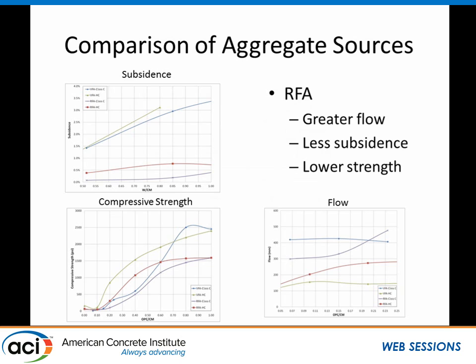Another main focus was to get a handle on the comparison of our two aggregate sources. And we were pleased that we found arguably benefits from using the recycled fine aggregate versus the virgin fine aggregate, insofar as we saw greater flow, less subsidence, lower strengths when using these recycled fine aggregates, all things that work in our favor for this class of material.